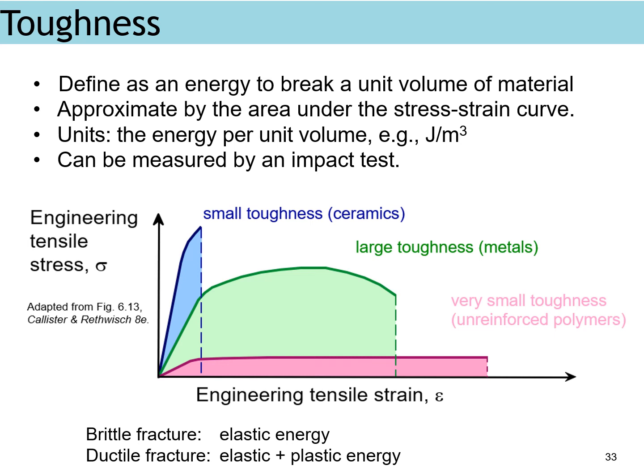Toughness is a fundamental material property that measures the ability of a material to absorb energy and withstand the shock of forces. It is related to the area under the stress-strain curve. The unit for toughness is energy per volume, joule over meter cubed, and it can be measured by the impact test.